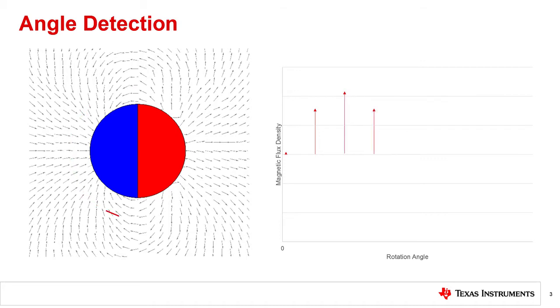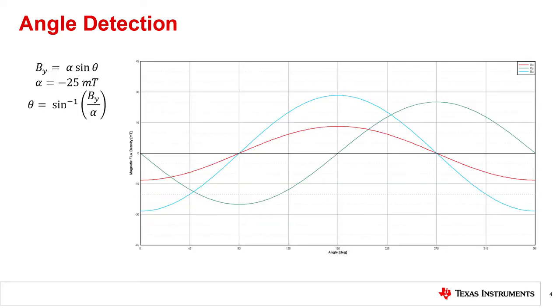When we place a sensor facing the pole of our magnet, we can trace out a path around the magnet and examine the field vectors as if the magnet were rotating. We notice, as the sensor is exposed to the magnet at various angles, that the resulting plot of field strength versus angle appears to be sinusoidal. With a single sensing element, we can use this behavior to perform a rough angle calculation.